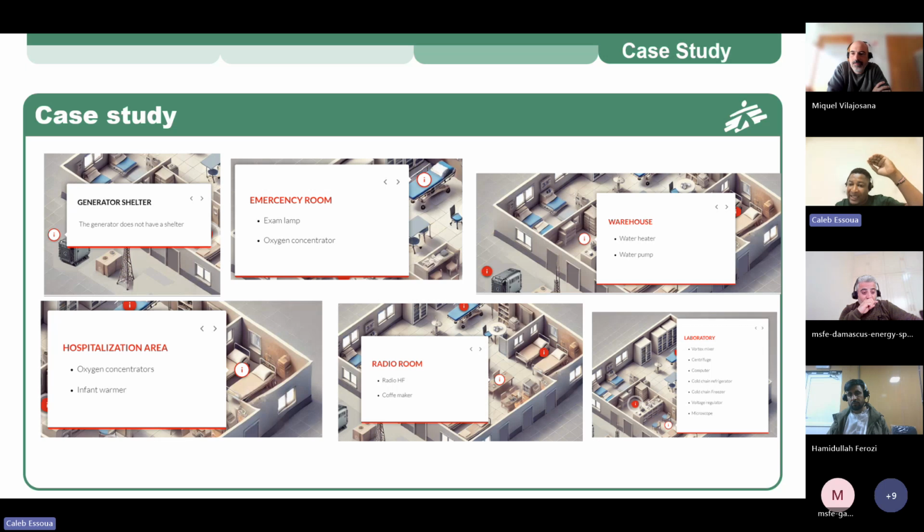Sometimes you see that nothing breaks down now, but in the long run, your generator will start acting up. The output of your generator will not be stable, and even if you have your AVR there, it will not be a good output. The same thing, this unbalanced load will affect your biomedical equipment and other electrical equipment. That's why it's always important for you to balance the load.